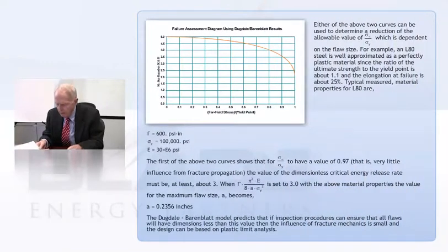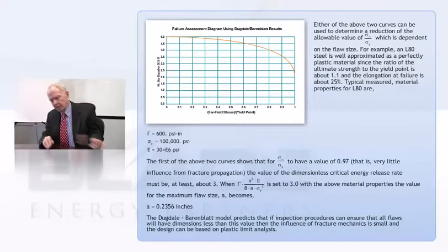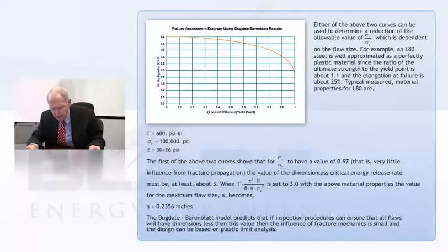So the next page, our slide, gives a plot of this, and it's kind of an interesting plot. You've got a ratio here. Let's see. That ratio is a calculated value to a measured value, and it starts at 1 when the far field stress is very low. So you can go very low on this because you have a singularity, and no matter how low the stress gets at the tip of the crack, you would have a singularity. But you can see that the ordinate here is telling you how much of the material property you can use. And when you start out, you might as well just use brittle theory, because this thing is almost 1.